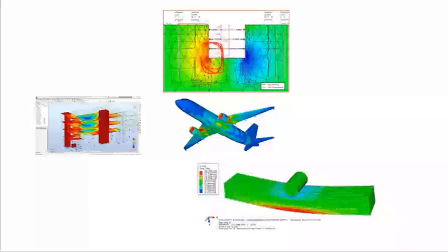So once you know the maximum stresses, you can really design your material to carry those stresses so that it doesn't fail. So you see what is happening here. The designer has just broken this material into a finite number of elements so that they can analyze this element.